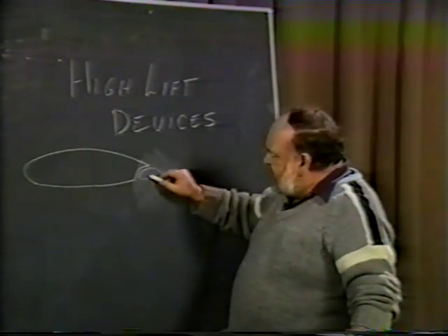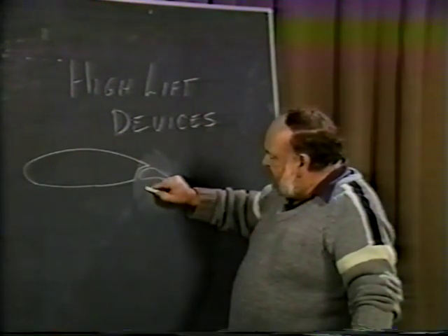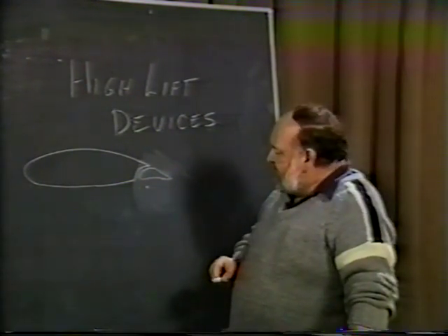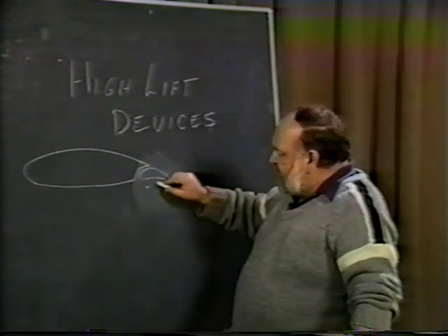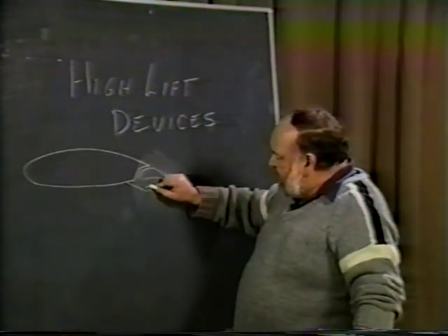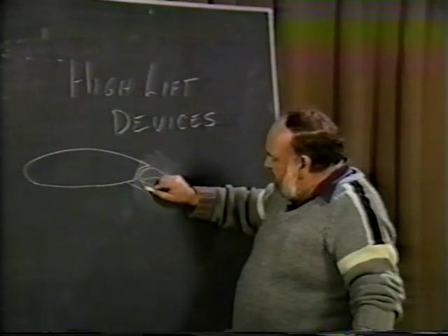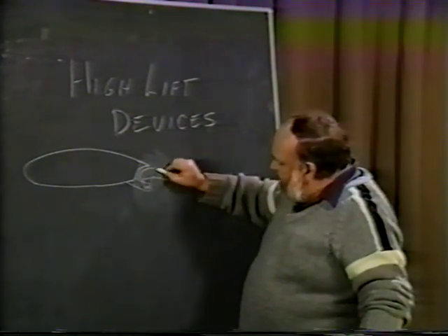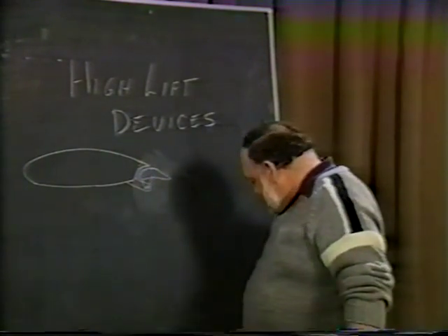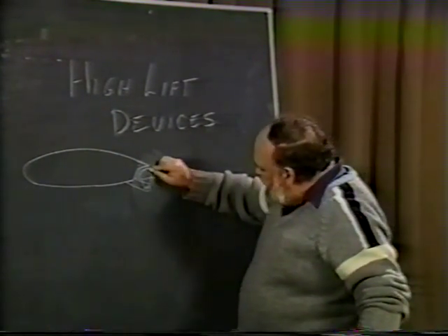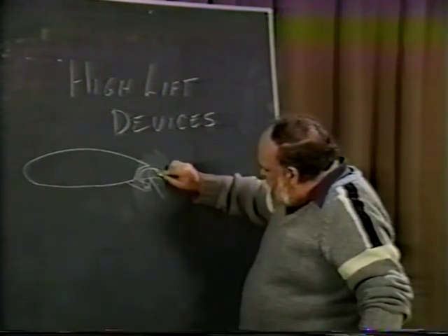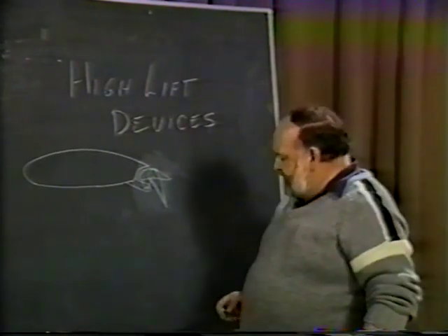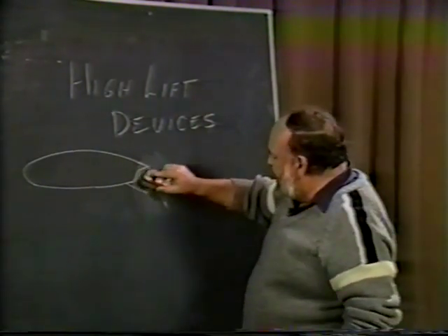And in this particular case, generally speaking, you do want to hinge it at a point that's outside the airfoil, generally at a position somewhat lower than the bottom skin of the wing, and therefore you probably have to end up with a bracket assembly that will control the flap. And then this flap pivots back, and in the deflected mode, will look like this.